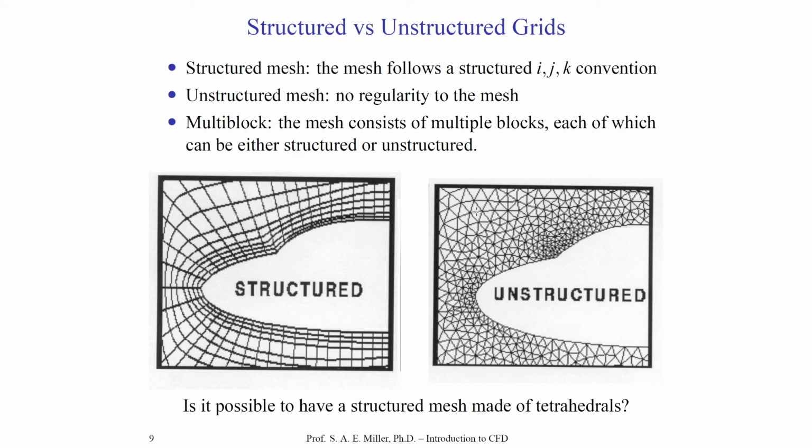There's other advantages for the solvers that use unstructured meshes. Typically, you can have much more complicated geometries in unstructured mesh versus structured mesh. Often, the order of your solution and your discretization can be much higher for structured type solvers. You'll have to balance and decide which one's appropriate for your problem. Typically, a solver can only use one type or the other.